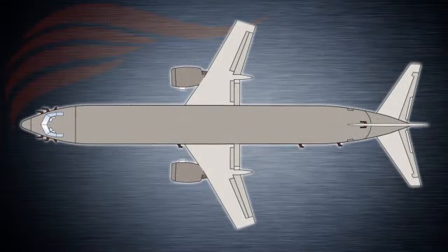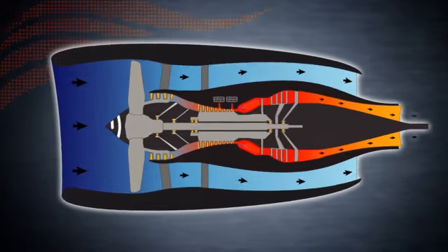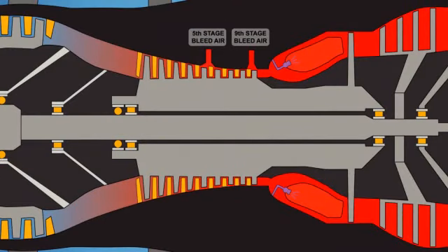Both the wing and engine anti-ice systems use engine bleed air to heat surfaces vulnerable to ice buildup. We cover bleed air in considerable detail in the bleed air system lesson, and since this has its own section, we will only give it a very brief explanation now. In short, bleed air is very hot, highly compressed air taken from the engines that is used by several aircraft systems. Under most conditions, bleed air is taken from the 5th stage of the high-pressure compressor section. In some cases, however, such as low power settings, this may not be adequate to cope with demand. In such cases, bleed air may also be taken from the 9th stage.